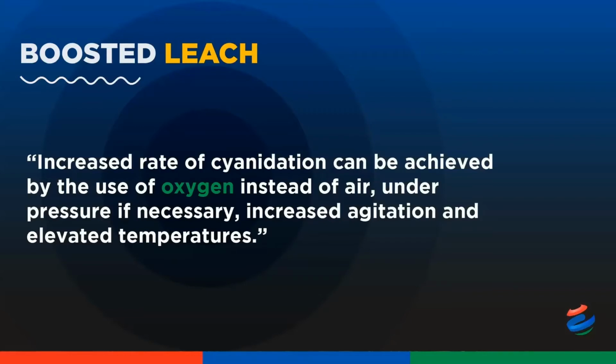A desirable situation which provides for high carbon loadings for elution and low soluble losses as the leaching is complete very high up in the leach train. Some precautions have to be taken if there are preg robbers present in the ore.